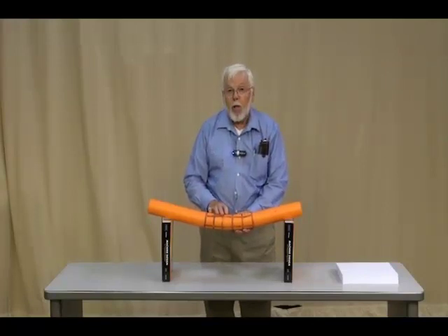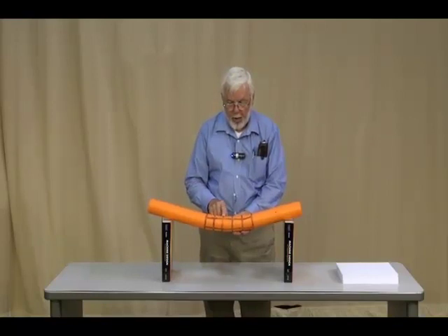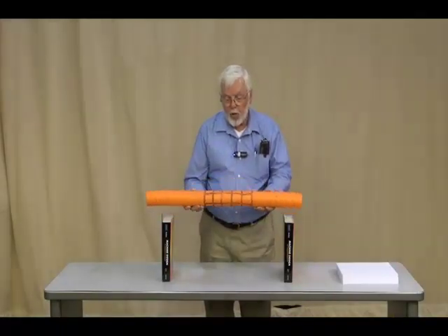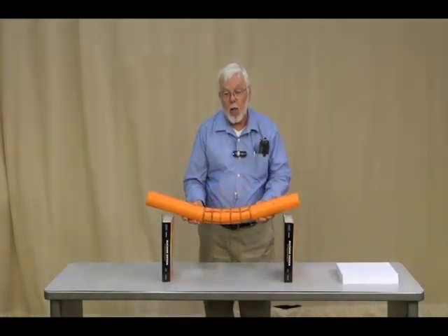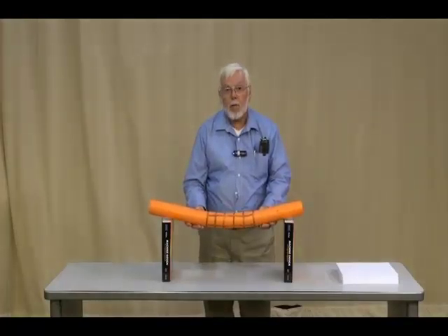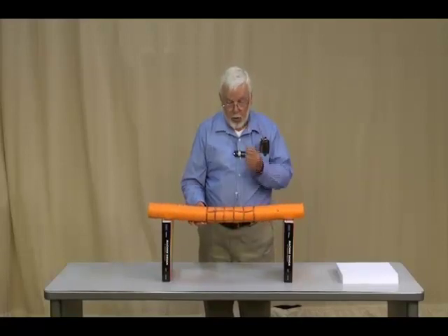So that represents how the bending stress, so-called, is distributed across this cross-section. And I'll show you a sketch of that in a minute. But the top surface or the bottom surface, depending upon which way I bend this, one surface will be in compression, one will be in tension, and at the neutral axis there will be zero stress. Now this stress is of the type we call normal stress, the ones I demonstrated on the cube pointing outward from the surface.